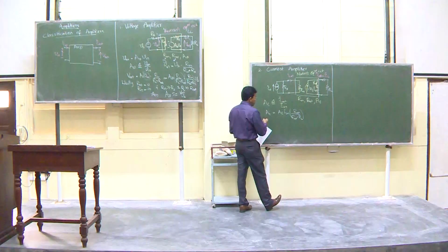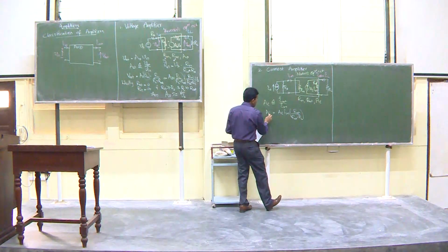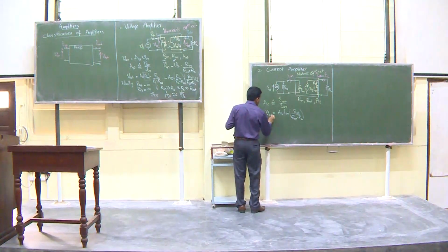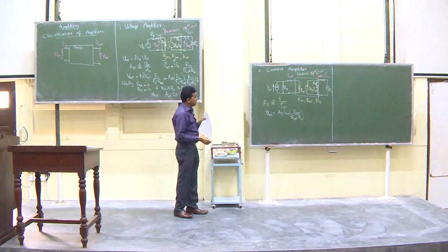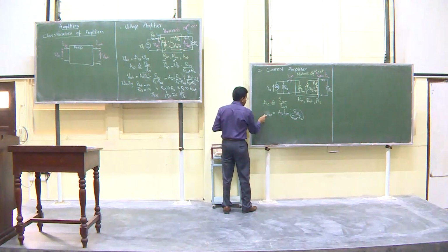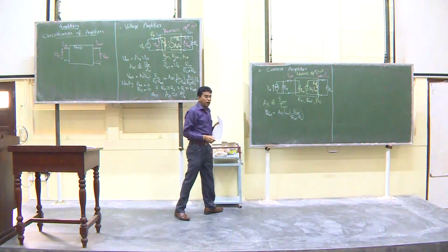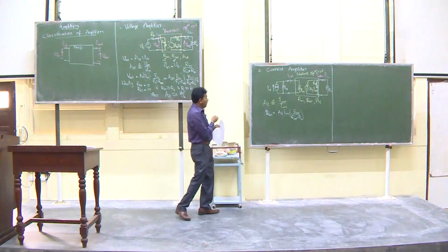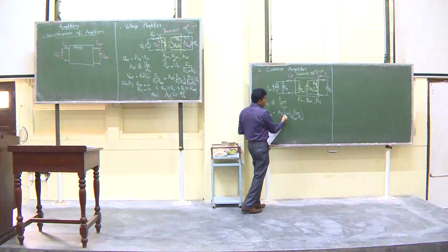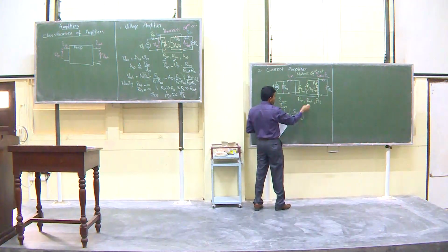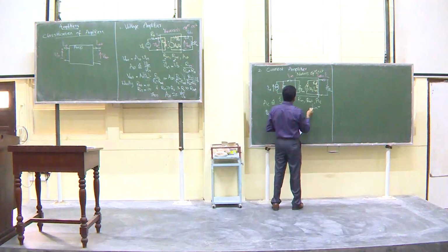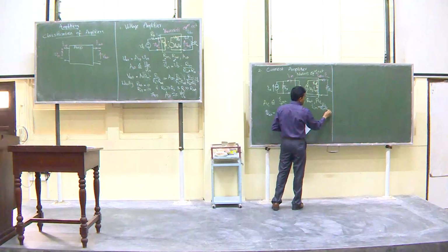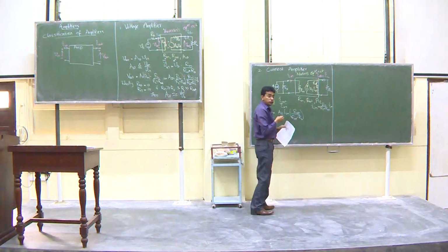Sorry, this is V out. V out is equal to AI, so I out is equal to AI times I in times that. And again, likewise, we can represent I in as Rs over Rs plus R in times Is, right.